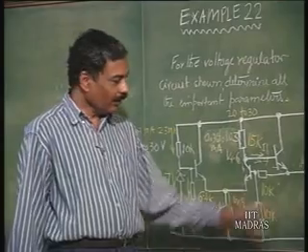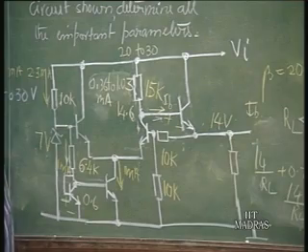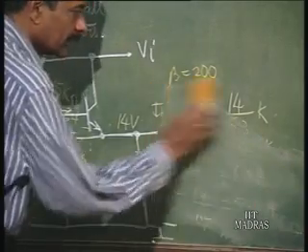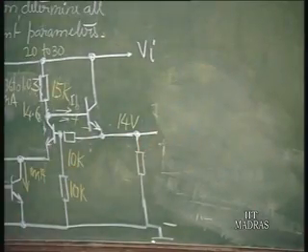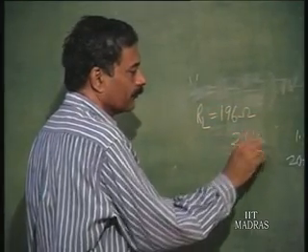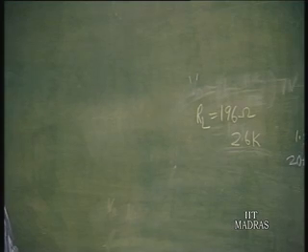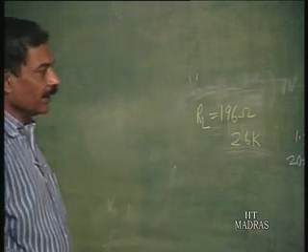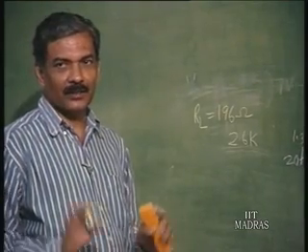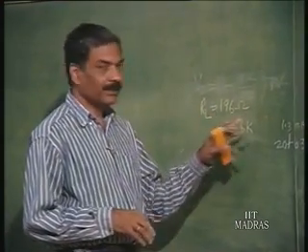That is one way of designing, or you restrict the load resistance to change from 2.6 K to 196 ohms. So load resistance can vary for this particular problem from 196 ohms to 2.6 K before it starts malfunctioning. So let us consider that the load under consideration normally is a constant, let us say. Let us discuss other parameters for a constant load. This is the variation of load.